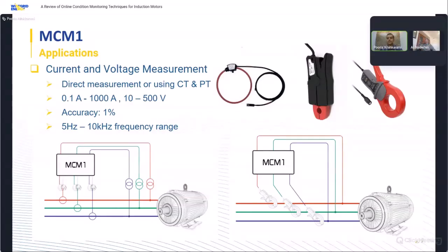Usually, for the test we perform, we take the samples up to 60 or 100 seconds to detect the full spectrum of the motor, to observe 0.01 hertz resolution in the spectrum. But the broken rotor bar, as we call it, will usually show up around the fundamental frequency of the motor, around 50 hertz.